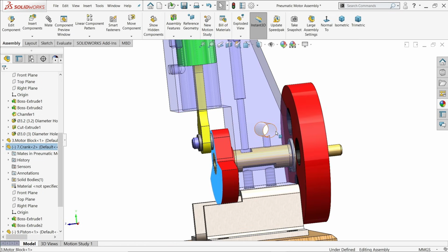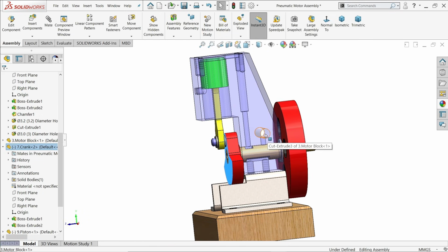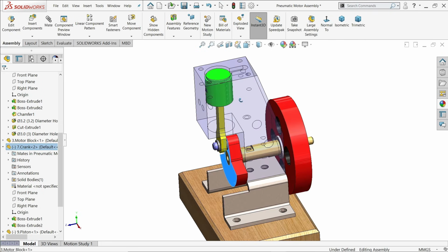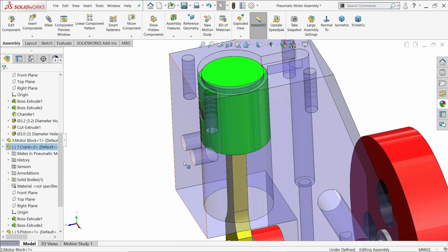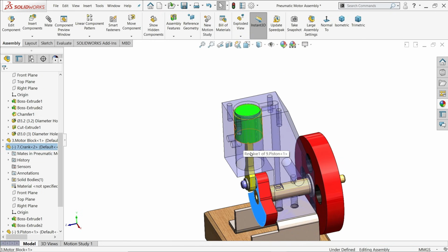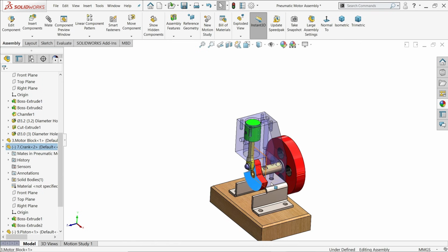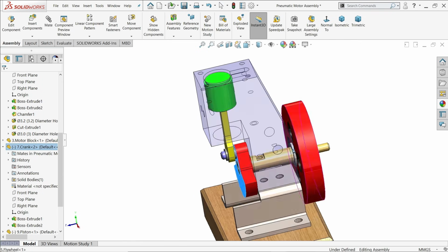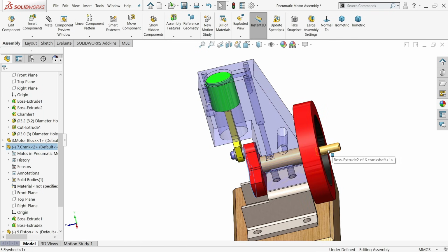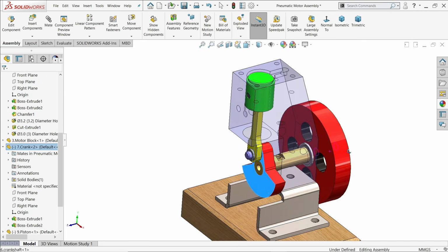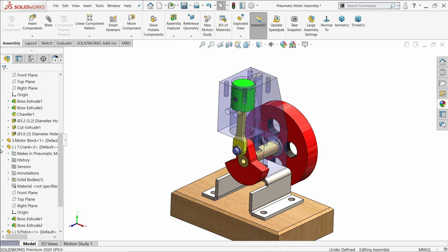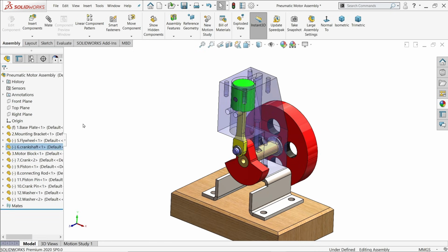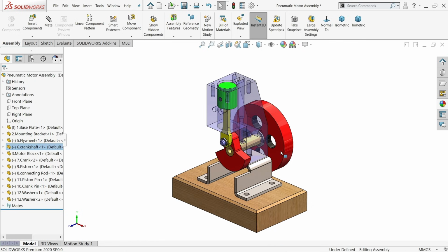So this is the main inlet for air. This air will pass through from here and come at the top and push this piston downward, and this is the exhaust hole. With the help of compressed air this engine is going to move, and the flywheel will help, and we can give a rotational revolution to any mechanical part. It creates a small amount of torque, but it can.